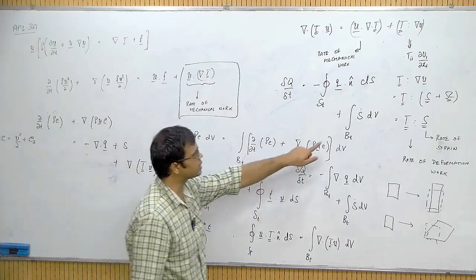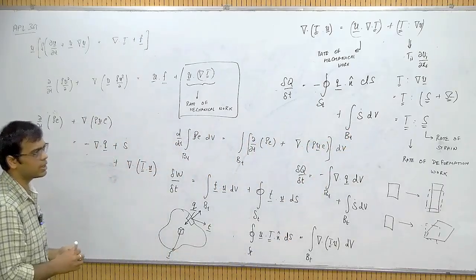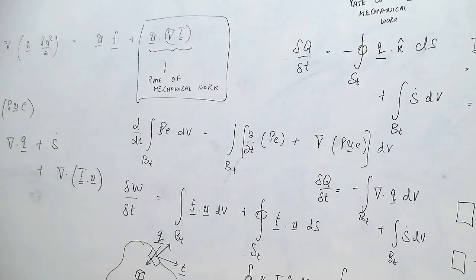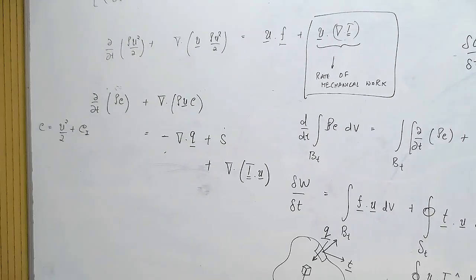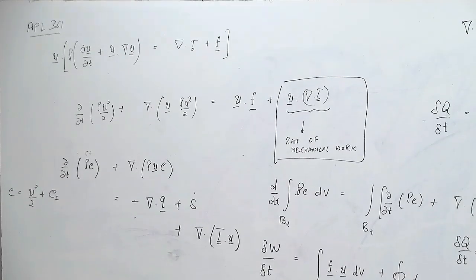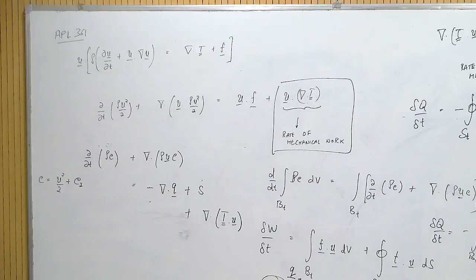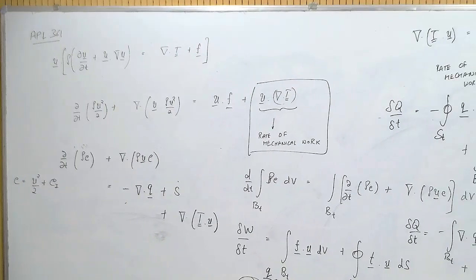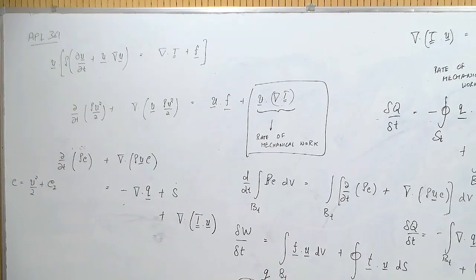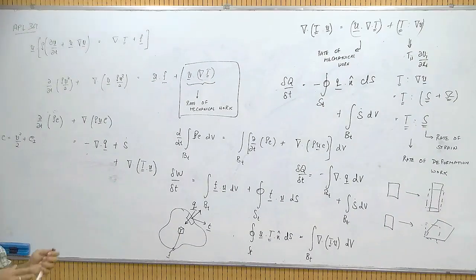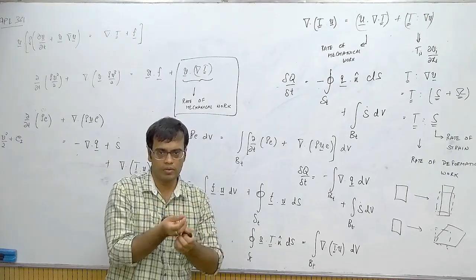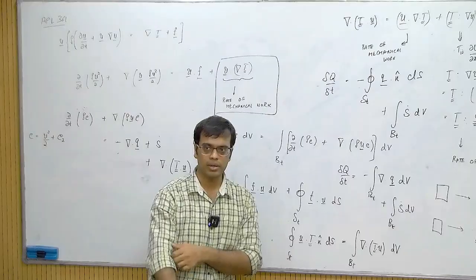and then the second one is volumetric heating. So think of, let's say, a chamber which has hydrogen and oxygen and you are igniting it. Let's say everything is at the ignition temperature, there's no heat going to be added from the surroundings, but due to chemical reactions which are exothermic in nature there might be heat addition to the fluid. That is what volumetric heating means, that due to chemical reactions or some other thing there is some heat added in the volume which is not coming from the surfaces. Okay.